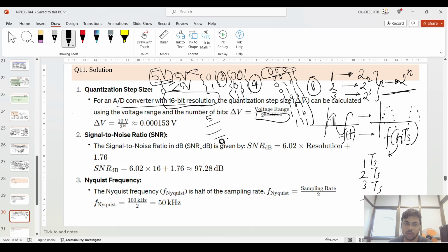Then you should define the 4 levels between 0 and 5. So 5 minus 0 divided by 4 is 1.25. If you go above 0 to the 1.25 level, then a certain logic will follow. If you go above that, to the 2.5 level, then another logic will apply.